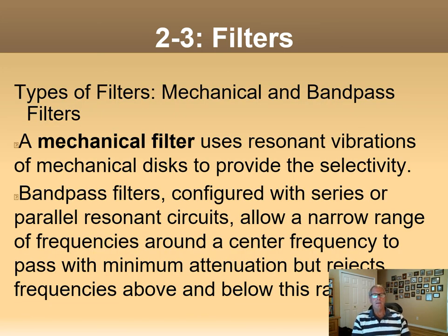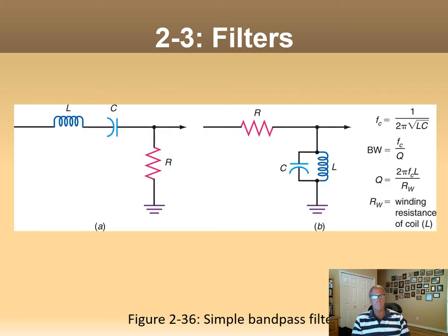Don't see many mechanical filters. I made one when I was doing radar a long time ago for really high power applications. We're talking many kilowatts, where your regular inductors and capacitors wouldn't work. They're basically tubes with Teflon and discs in them. They look like pipes. Okay, most of the time they're bandpass filters.